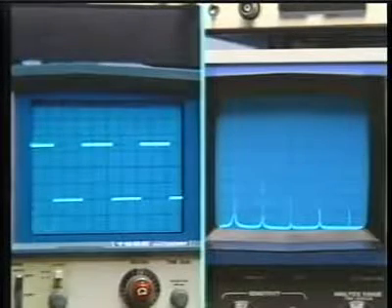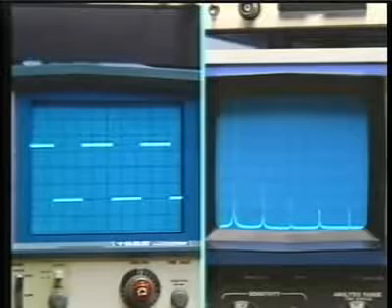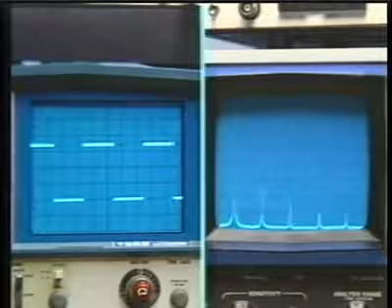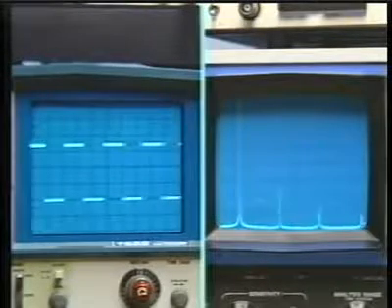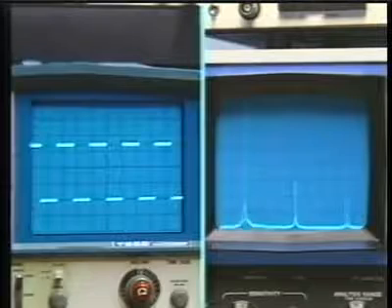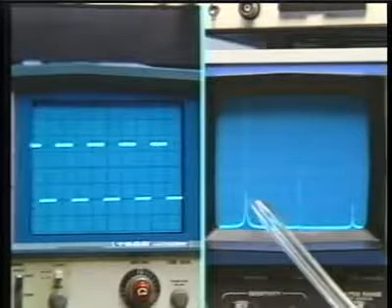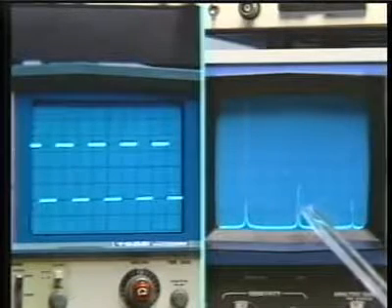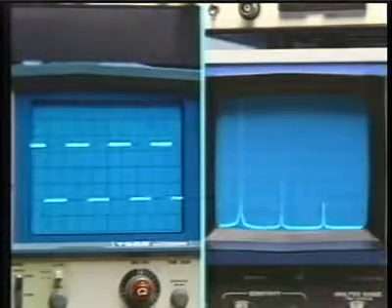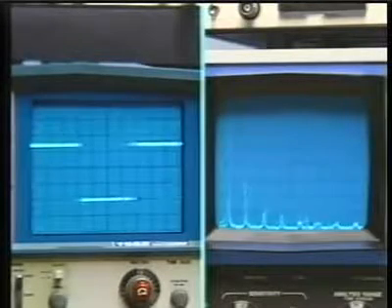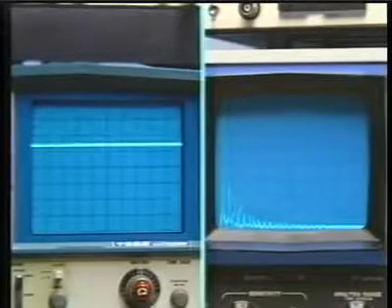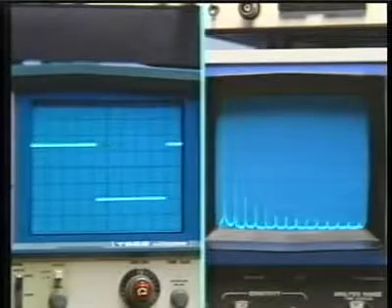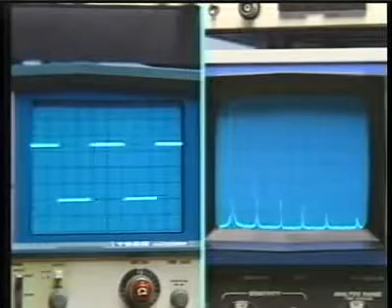While we're at the square wave, let me fiddle with the frequency of the square wave, and we can see the duality of the time and frequency domains. That is, as you compress things in the time domain, such as this, going to a higher frequency square wave, the harmonics wander further away from each other. So this is the fundamental. The second harmonic is missing. This is the third harmonic, and of course the fifth. And as we take this to an extreme, by going to very low repetition rate square waves, all those harmonics come scurrying in and cluster together near DC. Kind of fun with Fourier transforms.